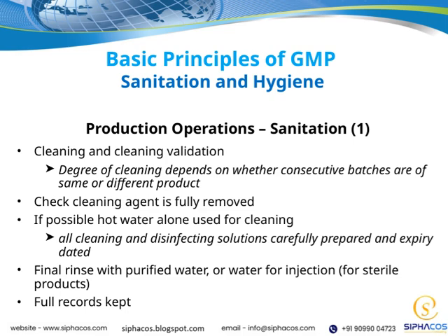It's also crucial to check that the cleaning agents we use are completely removed before moving on to the next batch. If possible, hot water alone can be effective for cleaning, which simplifies the process and reduces chemical residues. All cleaning and disinfecting solutions must be carefully prepared and clearly expiry dated, so we know they are effective and safe to use. After cleaning, a final rinse with purified water is essential, and for sterile products, we use water for injection to ensure maximum purity.